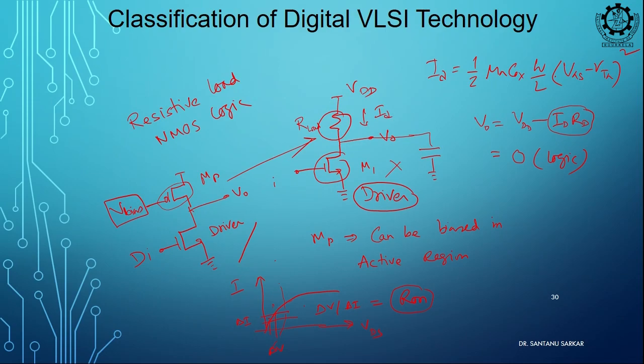So, this is just a replacement of this resistance. Okay. In this domain, this transistor is in which region? Saturation region. Can you tell me, saturation and linear, where the resistance is more? In saturation the resistance is more, because ideally dI is 0. So, ideally it is infinite, right.